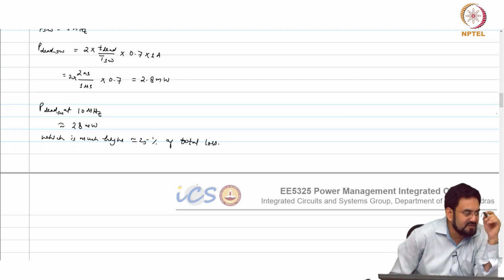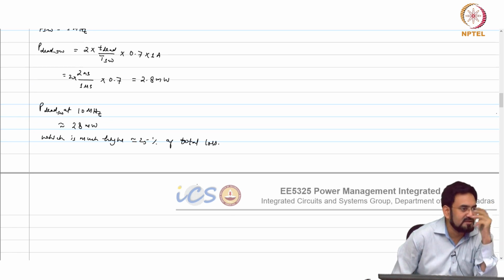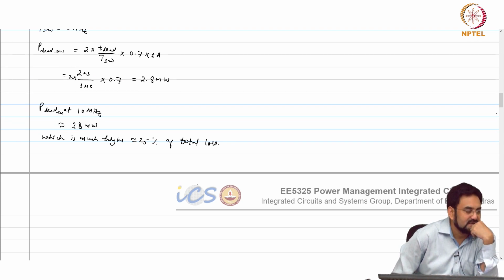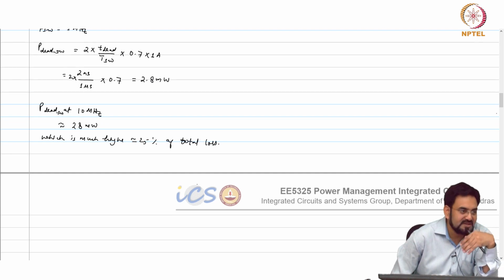Okay, so that is why, if you remember that curve, which loss dominates at what load, depending upon that, you have to make sure your switching losses are not that high at light load. So, let us say at 100 milliwatt, you lose 25 milliwatt in switching losses total, then what is the point? Your efficiency will be very bad in that case. So, 75%. Even though your I square R losses will be negligible in that case, you have to make sure that this does not dominate. It still remains roughly 10% of your total load.